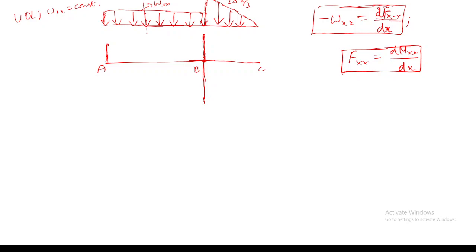If you take a cross section like this, then this is 10 and this is x, so it becomes 10 into x as the area of the whole shaded region. But here 10 is constant, everywhere you have 10 kilonewton per meter as the variation of the distributed load. That is termed as uniformly distributed load, right? Yes, sir. So here Wxx is constant.